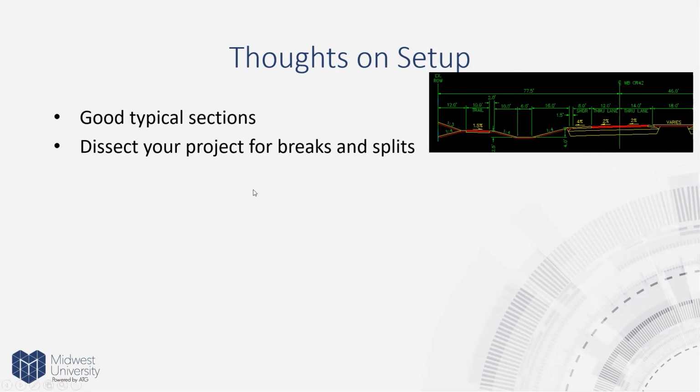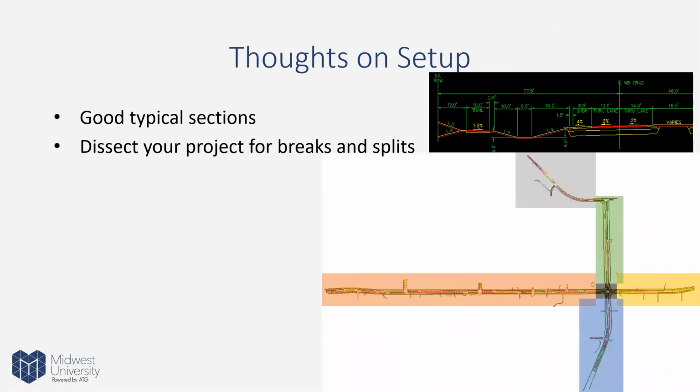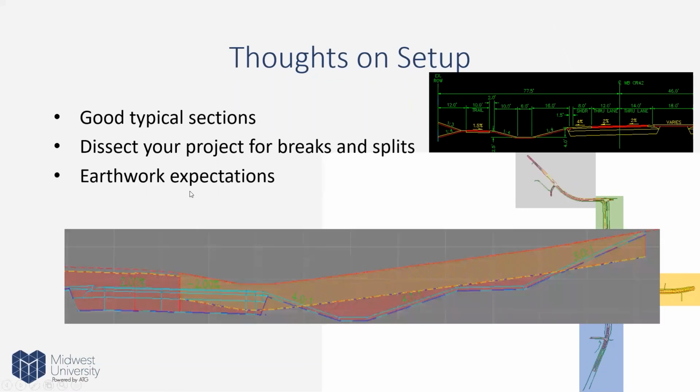It's always tough to think about what a good spot is to split up a whole entire project. Sometimes we might think it's this easy, but as you do corridors more, you can start to think of, would it be better to split up these given areas to allow the file itself not to get so big, but also thinking about how do I keep things contained so I'm not editing things in 5 different spots. So, there's no good rule of thumb there. It's kind of like what you feel makes the most sense.